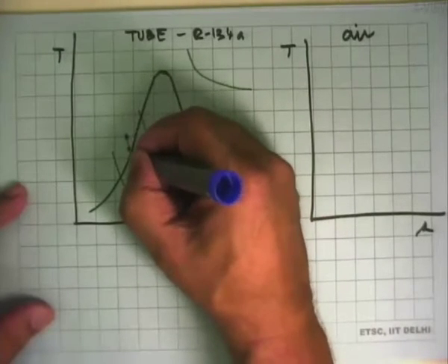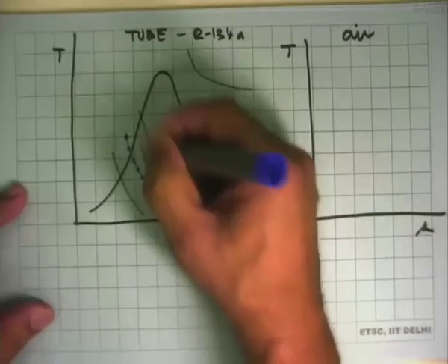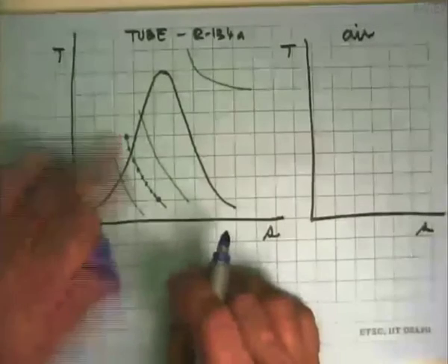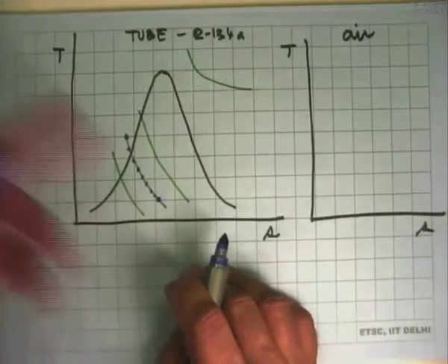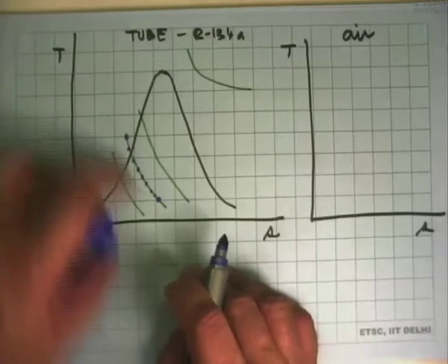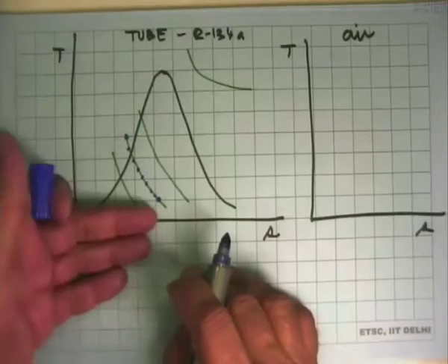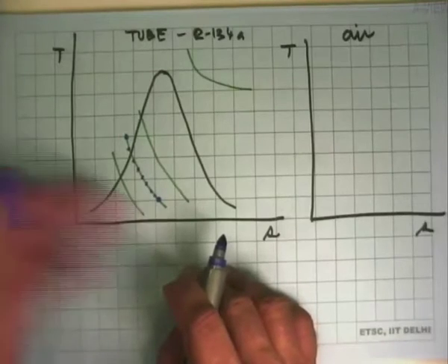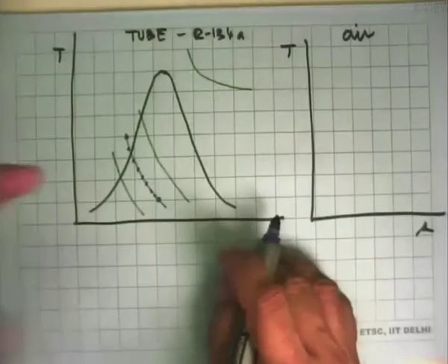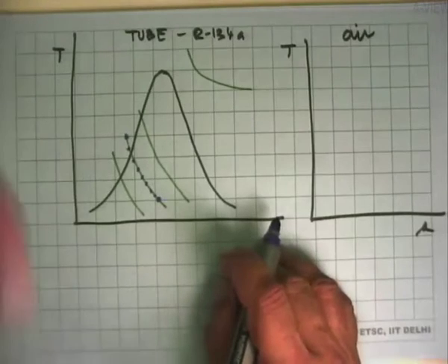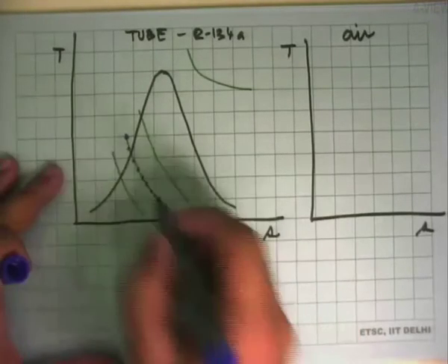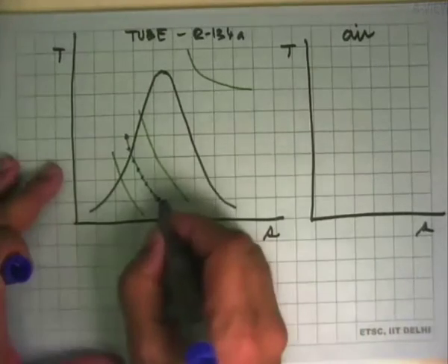One way to show it is that we put dotted or dashed lines along this line and say, look, it is irreversible. That's number one. That's why I'm not drawing a solid line. And second, I'm superposing it on the constant enthalpy line just to tell you that this is a constant enthalpy process. But otherwise, because it is irreversible, any other line is fine because the intermediate states are actually not known. So this is the inlet state to the evaporator.